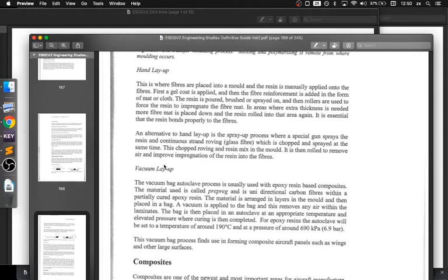So this is how we use fiber reinforced polymers, and when we use these, we have two main methods. Either we can just lay out the fiberglass, or in this case it can also be carbon fiber reinforced polymers, or glass fiber reinforced polymers. Whichever one it is, we can lay out sheets and then apply the resin just with a brush, or we can use something called an autoclave, and we put it in a bag called a pre-preg and put it together. We've got videos on that. We'll look at that later.